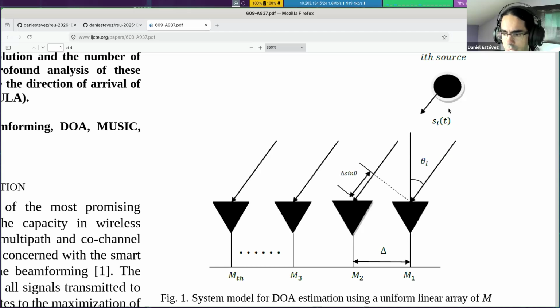And the second one depends on the type of antennas we use. In the Allen Telescope Array, we'll see dish antennas, which are the most common for the higher frequency bands. And dish antennas have a limited field of view. So for example, for the higher frequencies in the Allen Telescope Array, it's like 0.2 degrees on the sky.